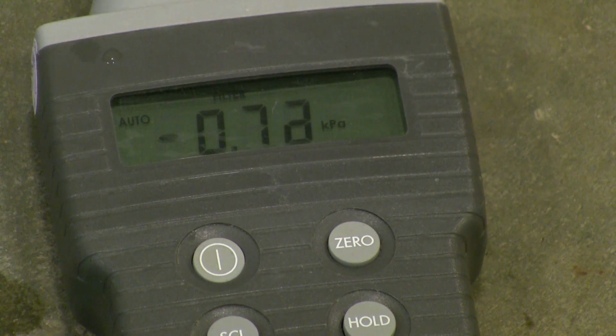Now these pressure differentials are going to be lower. Since we've got a reduced flow rate, we should expect there to be less energy loss. But in theory, the K values need to be independent of velocity. They are in fact supposed to be constants, and so we'll put that to the test and see whether it's actually the case.